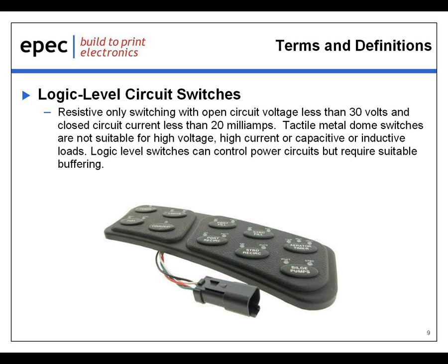I mentioned logic level switches a moment ago. A logic level switch array or keypad assemblies are resistive only switches, with open switch voltage of less than 30 volts and closed switch current of less than 20 milliamps. Tactile metal dome switches are not suitable for high voltage, high current, or capacitive or inductive loads. Logic level switches can control power circuits, but they require suitable electronics buffering. In other words, the dome switches interface directly with electronics rather than controlling the power circuits.